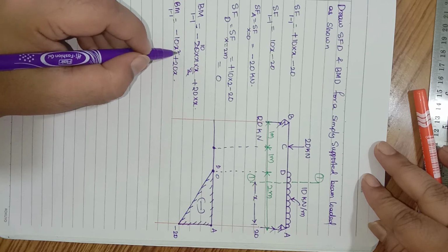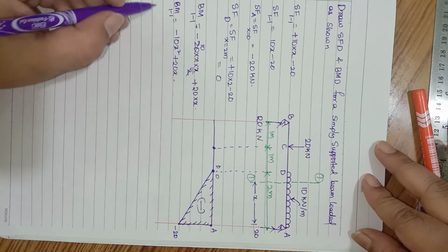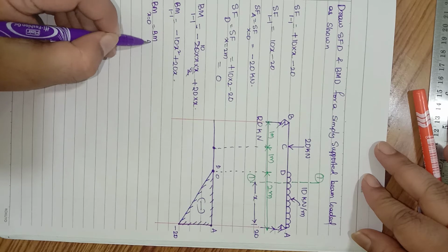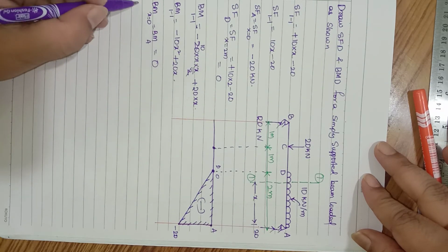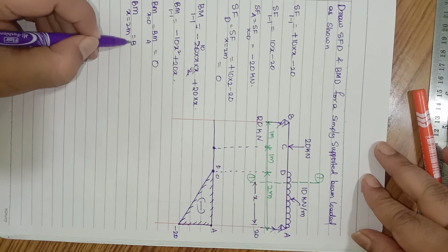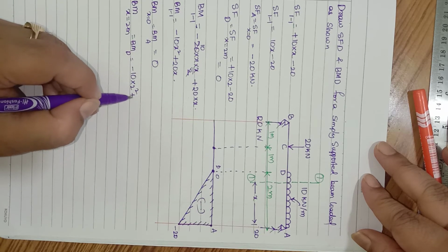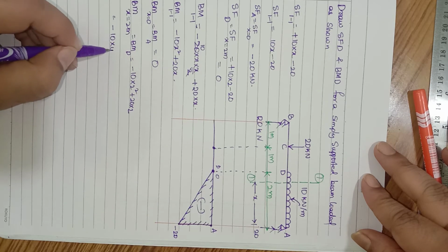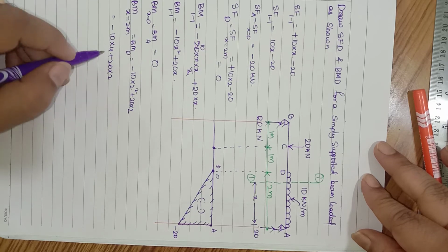So you can see the variation over here, right? It is a square, so the variation will be parabolic. Now bending moment at any section x equal to 0, that means bending moment at point A, that is 0. When I substitute x equal to 0 here, you will get the value as 0. Now bending moment at x equal to 2 meter, that means bending moment at point D. So it is minus 10 multiplied by 2 square plus 20 multiplied by 2. So this is minus 10 multiplied by 4 plus 20 multiplied by 2. 10 fours is 40, and this one is again, which is equal to,